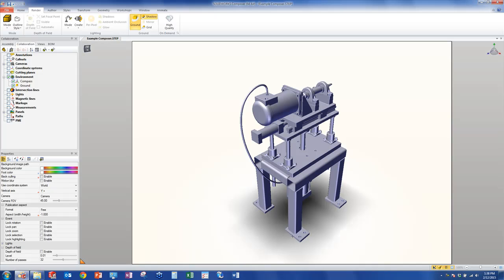Next thing I want to do is get the view of this the way that I like. To do that, I typically use the mode called Smooth with Outline. That smooths out the image and it also puts hard edges anywhere there is a visible edge. I like to change the output style to Smart Outlines. That way it gives it more realistic rendering and doesn't put a hard edge everywhere there's tangency.